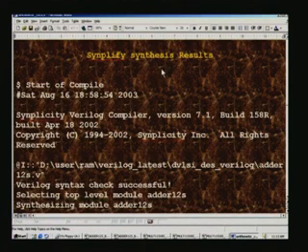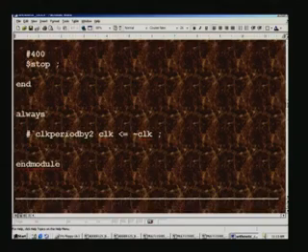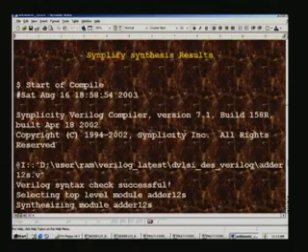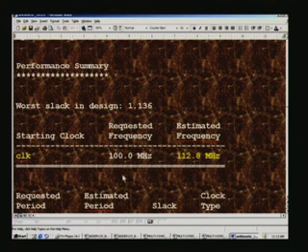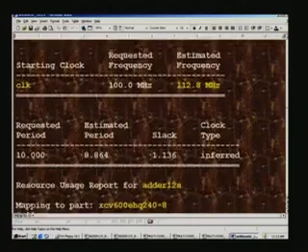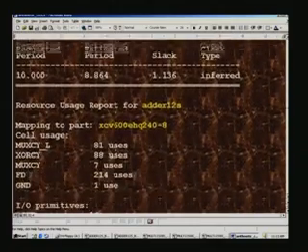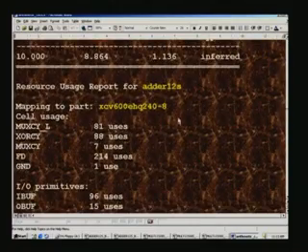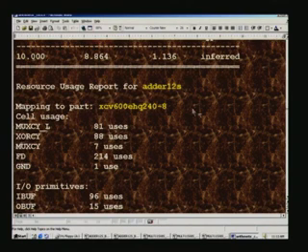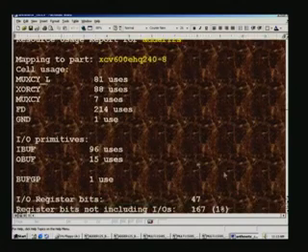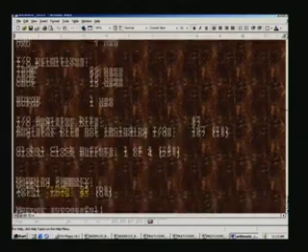simplify results for this. And so it works at a clock of 112 to 113 megahertz. These are the simplified synthesis results, and we have mapped as usual on the standard device for the reasons we have mentioned earlier, and this is the design, and various internal primitives are all listed here, and finally a number of LUTs will also be listed here.